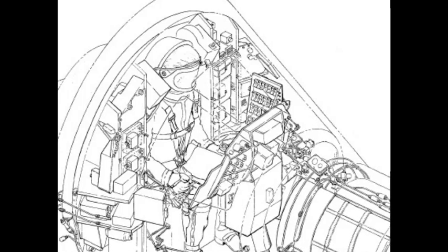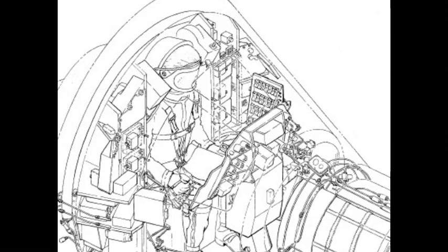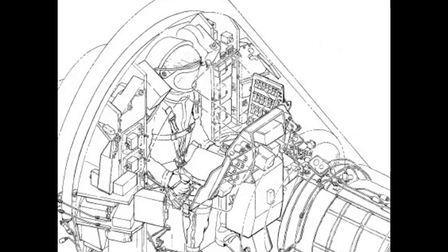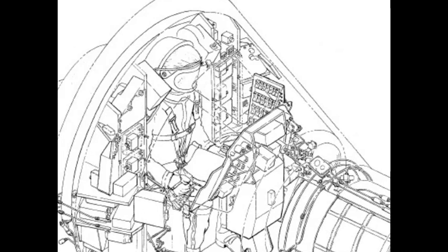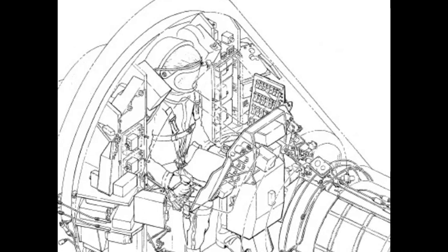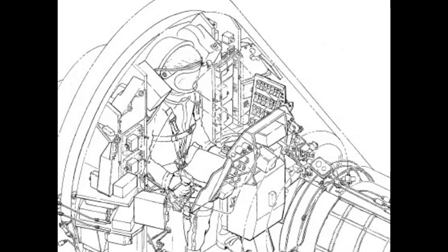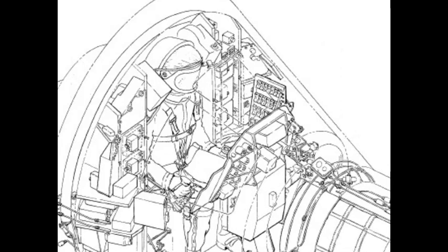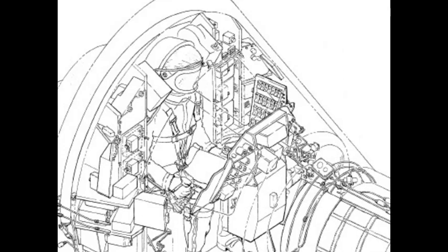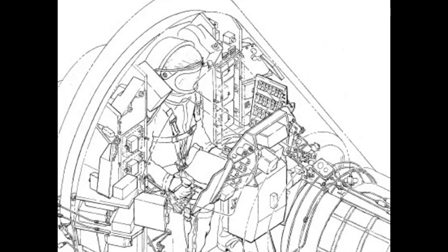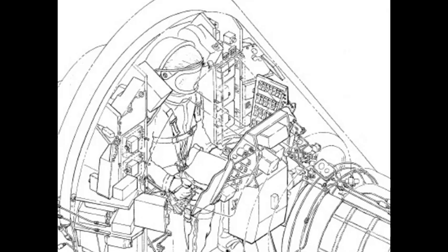The dish-shaped escape hatch is constructed of a beaded aluminum skin spot welded to an inner skin that is reinforced with structural Z-shaped members. The hatch outer flanged edge fits into the small pressure bulkhead sill and is held in place with a retaining ring. Expanding the retainer ring by raising the hatch handle wedges the retainer ring between the bulkhead sill and the hatch flanged edge and forces the hatch flange aft to provide a sealing action. The titanium small pressure bulkhead is seam welded to the conical section inner skin and bolted to the conical hat stringer flanges.